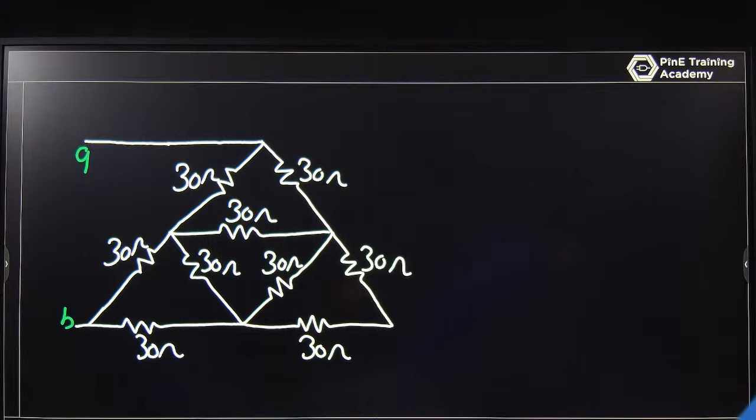And second, the output impedance is zero, so it acts as a dependent voltage source and the main output voltage stays the same. Ideally we want output impedance zero and input impedance infinite, but practically it is not. So that's why this analogy is very important.